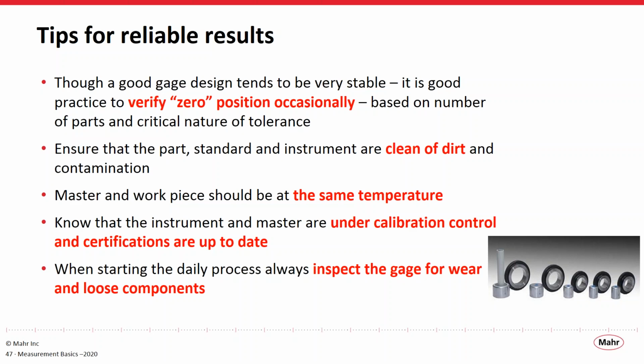Again, at the start of the day, during the day, and at the end of the day, clean any dirt off the gauge, off the workpiece, constantly trying to battle dirt and get it off the gauges. Even letting a gauge sit overnight, you might clean it before you go home at night. You come back in the morning. There's a good chance that there's a thin film of oil or dirt or dust on that gauge that should be wiped off and re-zeroed before you start making your daily measurements.